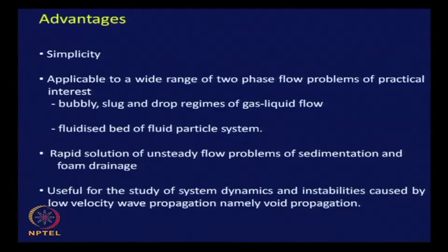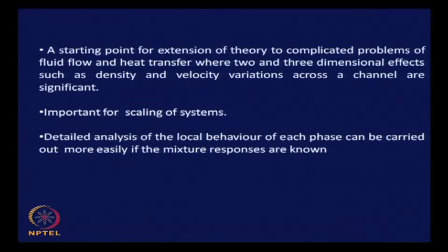You will find that the equations are much more complex, you take much more time to solve them, they are much more elaborate, and so naturally we will definitely do it. But at that time you will feel that the drift flux model was a much simpler approximation, and the error introduced as a result of this simplification is not very large. But definitely if you want to use the drift flux model for stratified flow or annular flow, you will not get a correct result. So, these were the advantages of the drift flux model, which I have written down. But remember it is not applicable for all particular situations.